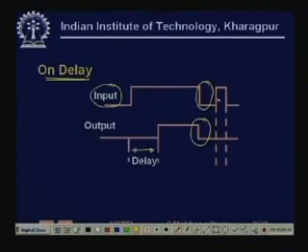Similarly, note here that again it becomes on. Now the timer, if this on would have persisted, then the timer would have been on somewhere over here, because of this delay. But unfortunately, or fortunately, the input became off even before this delay interval could expire. So the timer also became off, and that delay value got erased. So the timer never went on.